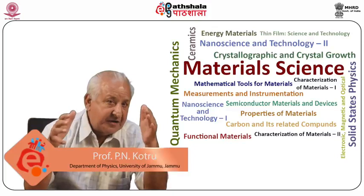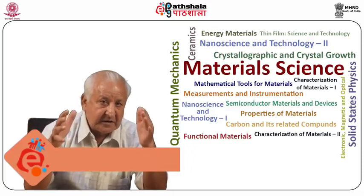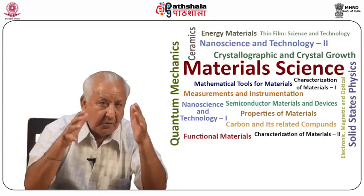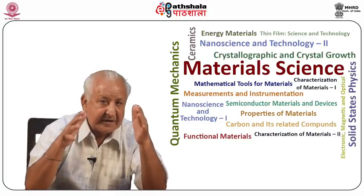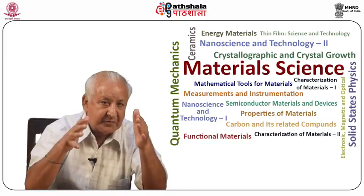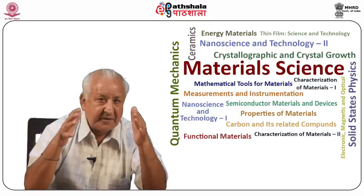The experimental arrangement for Czochralski growth is described. Other techniques of crystal growth from the molten phase, namely Kyropoulos, Dendrite, edge-defined film-fed growth abbreviated as EDFFG, and liquid encapsulation Czochralski techniques of crystal growth are described and discussed.